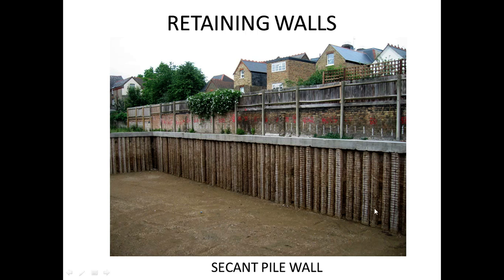Having done all that, we then excavate. Then we take the earth out from underneath. So we start by, if you like, perforating the ground with this series of holes and concrete columns, and then you take away the earth from underneath. And then you might put some kind of cage onto the surface. You'll probably spray concrete onto that to give it a nice finish.